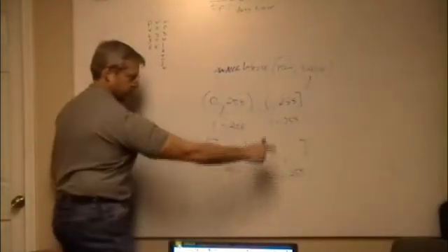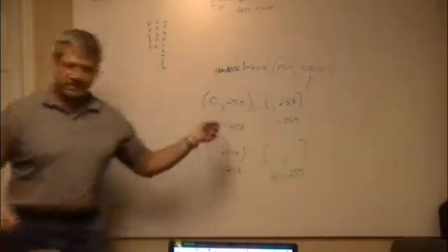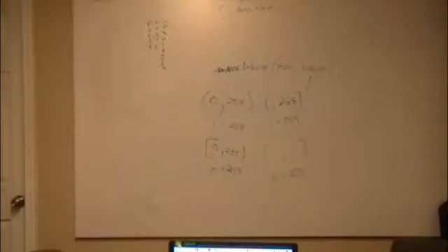So you see the four different... Gotcha, you're bounding the range. So I think that's right, you have to look it up yourself for the analog write. The analog write uses... it depends on which pin you use, if I remember the reference correctly. If you go to arduino.cc, under the learning, there's like 4 tabs across. I think one of them's learning and it has reference, and it basically has the standard reference library right there. If you go in analog IO, read about analog write, I think it uses 300 and some odd hertz on one pin, and it uses 1200 or something like that on a different set of pins.